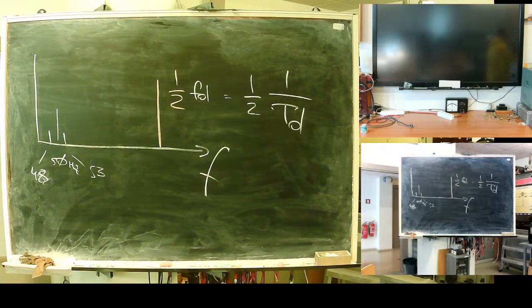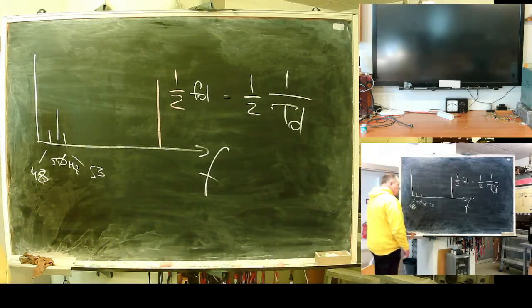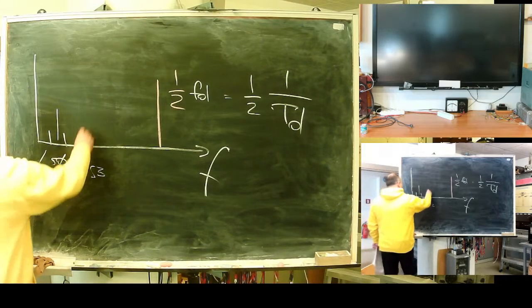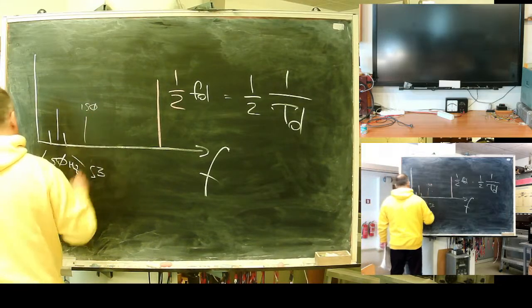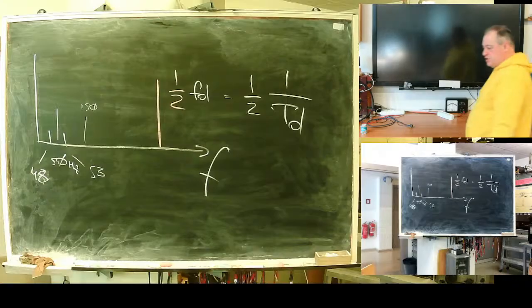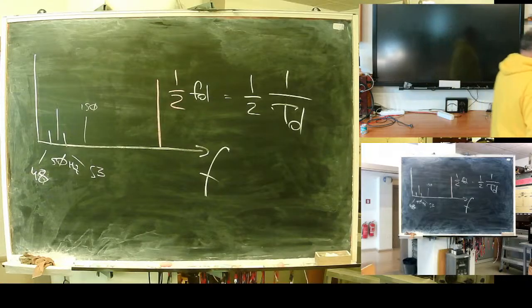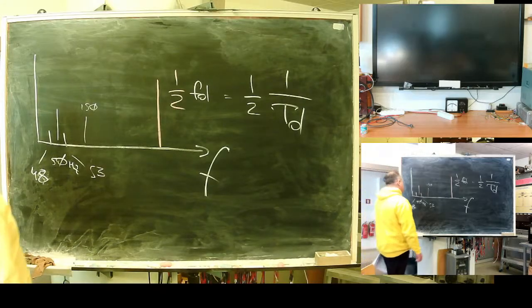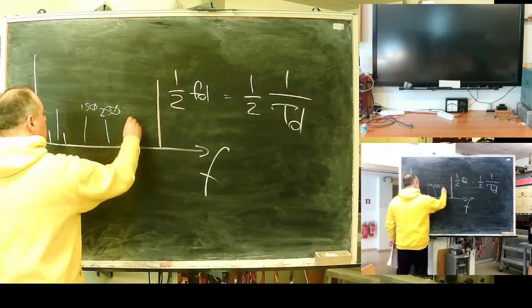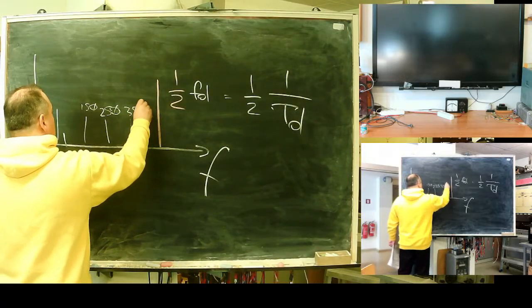But if you look deeper, you may need 150 for the case of Earth's fault protection, especially for distribution network. If you would like to have precise detection of current transformer saturation, 250, maybe 350, and so on.